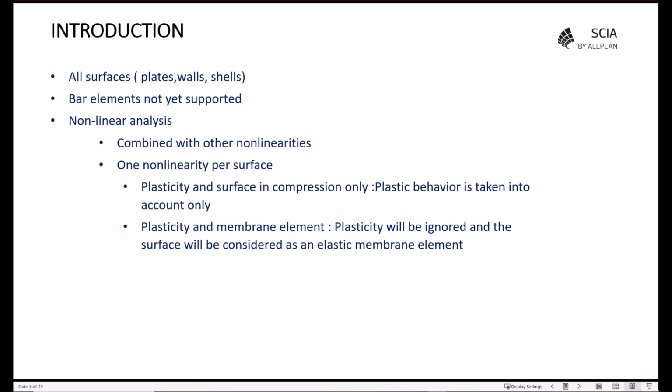It could be combined with other nonlinearities, but here we have one particularity. For the surface elements, we can have only one nonlinearity. For example, if we have a plasticity and a surface in compression only, only the plastic behavior will be taken into account. Another example, if you have a plasticity and a membrane element, in this case, the plasticity will be ignored and the surface will be considered as an elastic membrane element.